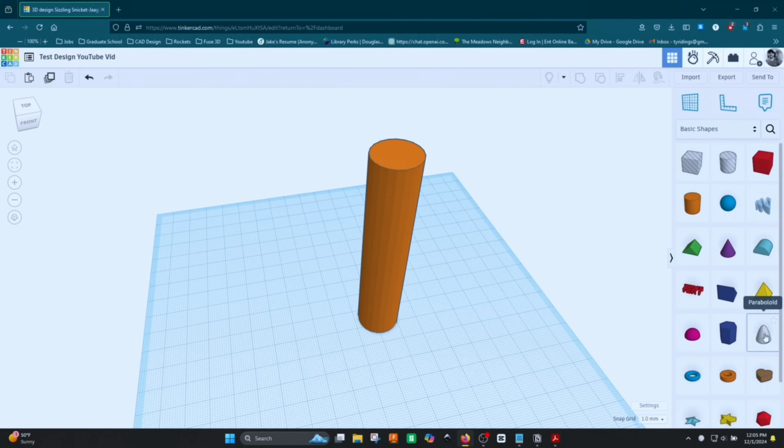This is a really cool feature now with Tinkercad where you can cruise your parts together. So what you do is you left mouse click and hold, and drag it out here, and see how it's kind of adapting to surfaces as I drag it. This is really nice so that you can pick the exact plane that you want to place this on. And for me, that'll be up here on top. So I'm going to place this and I'm going to leave it a little bit off-centered.